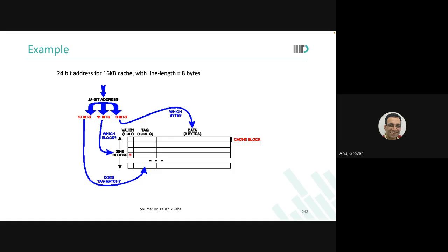So just now, when we were talking about coherency, just a little while back, this was what we were talking about. Suppose my same data is available in adjacent cores. There are multiple processors using the same L2 cache. Processor A had fetched data of a particular location. Processor B also fetches data from the same location. Both had not updated the data until now. Let us say processor B now updates the data.